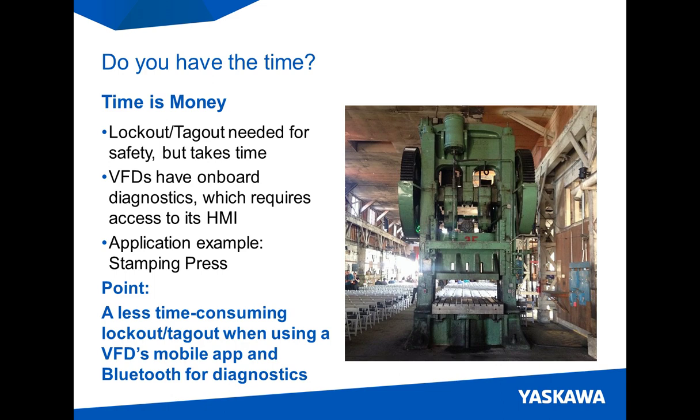And less time spent performing lockout, tagout to do certain functions means that it's better for everybody. So the technician could, for example, stand safely outside the exclusion zone of the equipment to monitor the VFD or check its fault history.